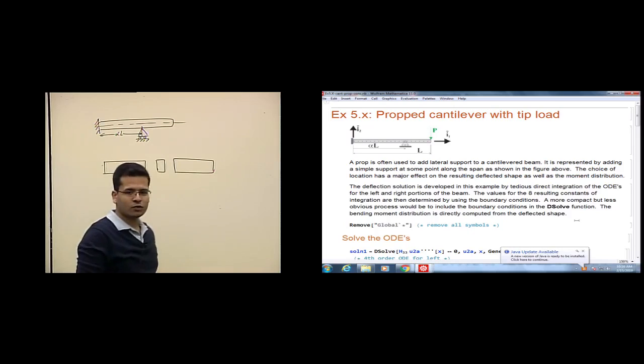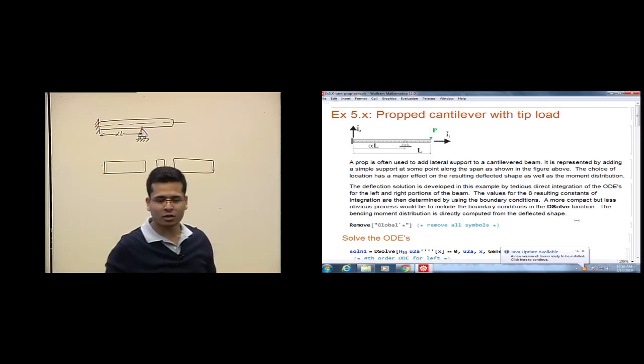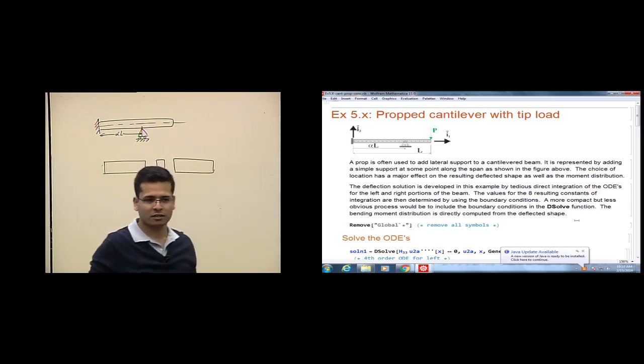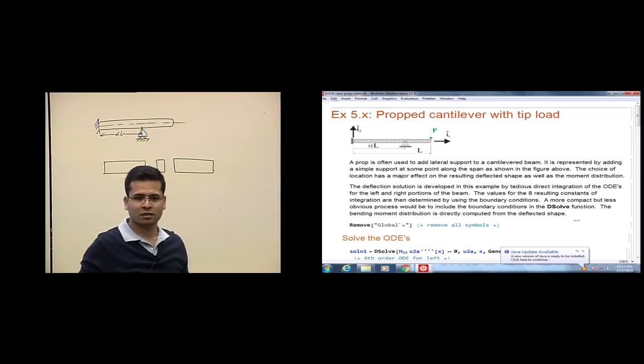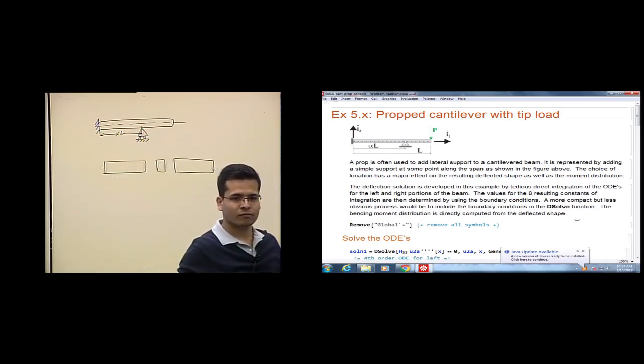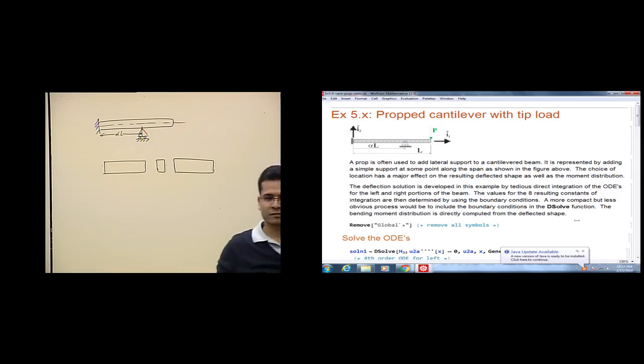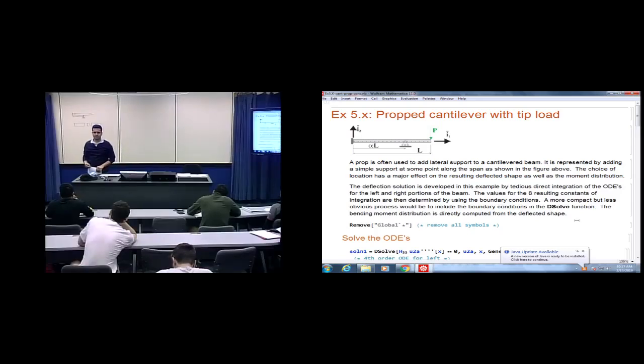Okay. So how many of you don't think that we need to write reaction forces here? You don't need to write reaction forces, because the reaction obviously comes out of the boundary condition. Like we're not writing a shear boundary condition at the end because there is shear, but we're going to have shear on the other end. So obviously you can find it. We do not write reaction forces here because the purpose is not to find moments in the middle of the beam.